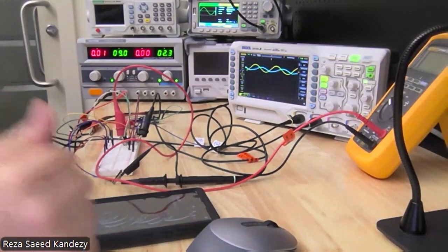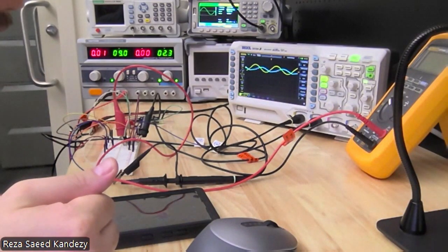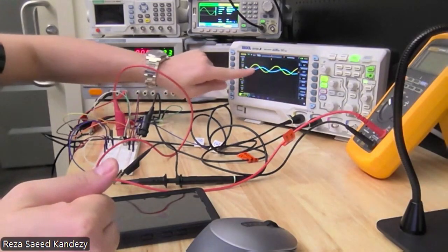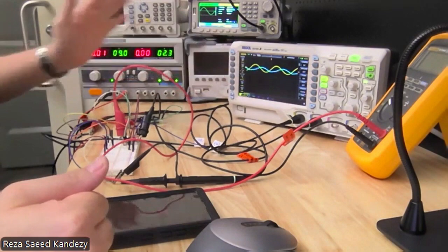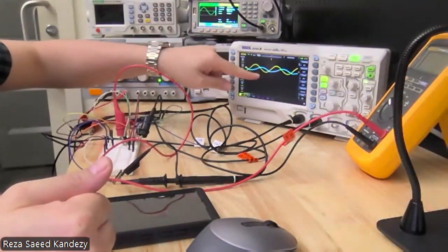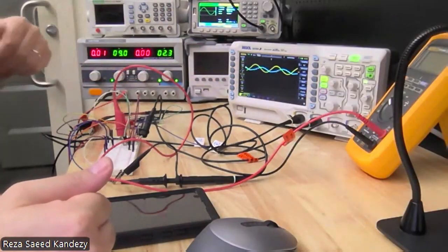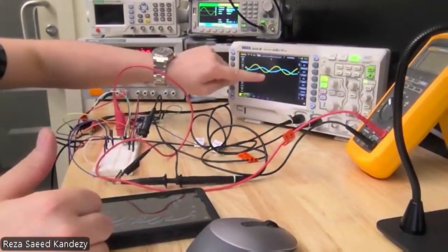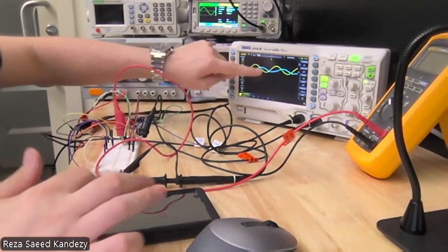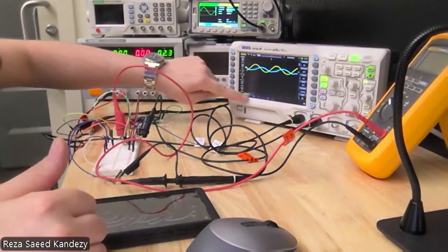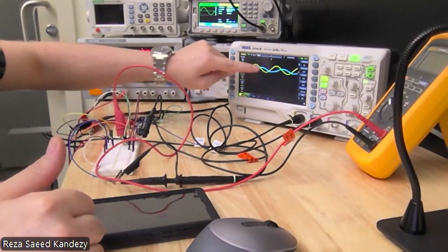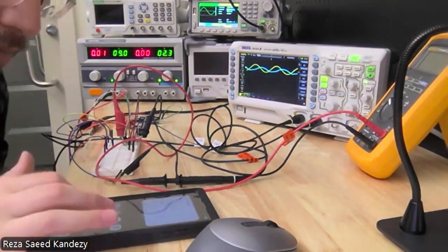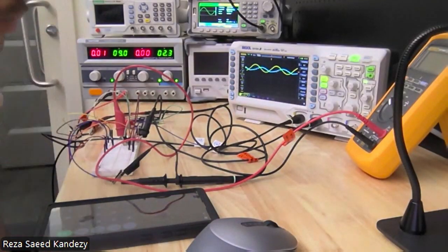So basically, that means I have a 3 volt peak-to-peak input. As you can see, my output, which is a little bit shifted, is not perfectly 180 degrees phase shifted, but it is shifted based on my input. This is one square, 1 unit of the grid on my oscilloscope, and my voltage division for channel 2 is 10 volts. So my output is going to be 10 volts and my input is 3 volts.